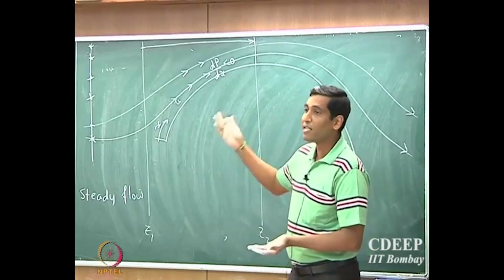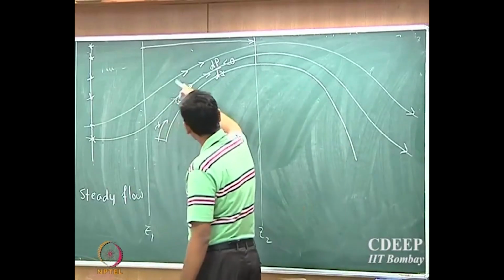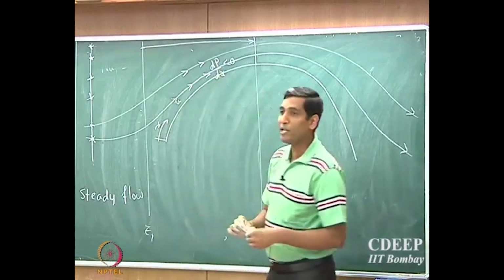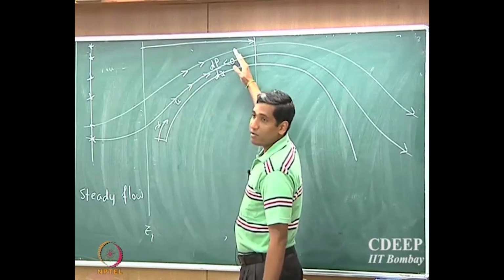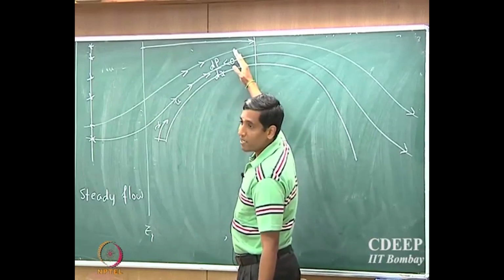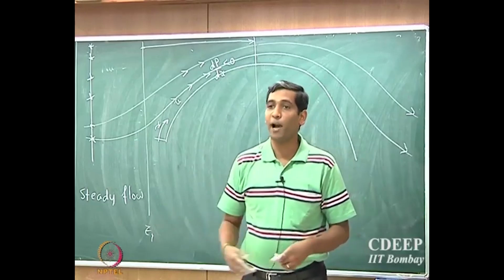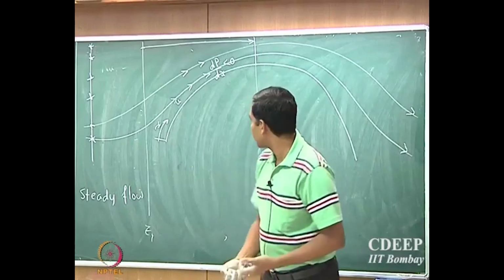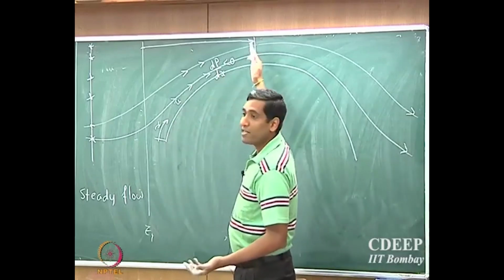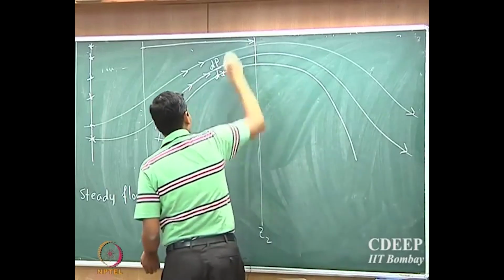This happens only till a certain location. The fluid particles will accelerate up to a certain location, and at some point, depending upon the magnitude of the upstream velocity, it's not able to catch up with the speed that it has to, and so the pressure gradient will go to 0.